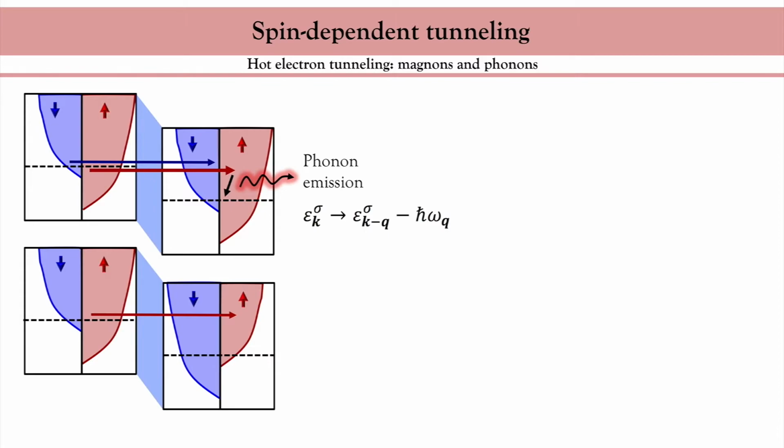However, remember that the spin of this electron points against the direction of the magnetization, so the electron can emit a magnon by flipping its spin. The spin flip transfers this originally up electron toward the large density of states of the down electrons. This mechanism opens a new channel that is dramatically efficient and reduces the TMR substantially.